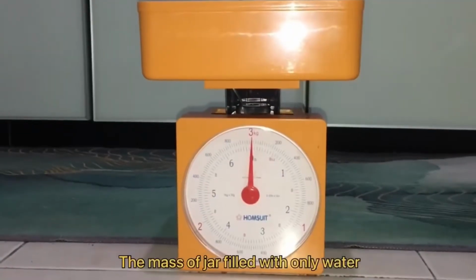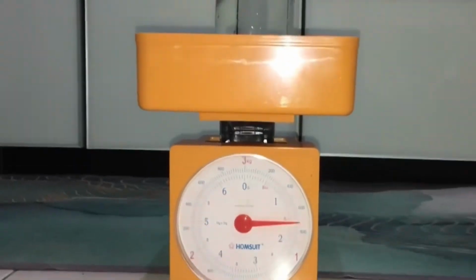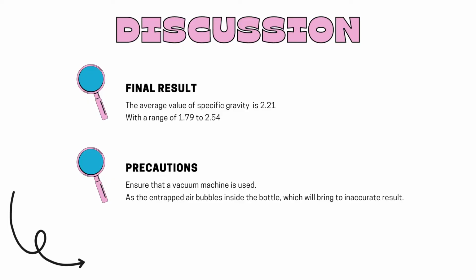The mass of the jar filled with only water is weighed and recorded as M4. This is the expected result that has been obtained for the particle density test. For discussion, the average value of specific gravity is 2.21 in a range of 1.79 to 2.54. For the precautions, ensure that the vacuum machine is used. This is to eliminate the bubbles inside the bottles that will bring inaccurate results.